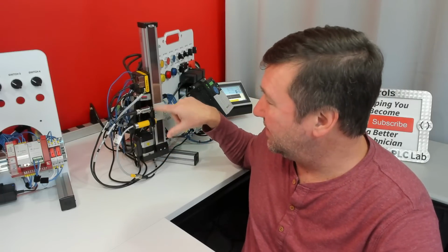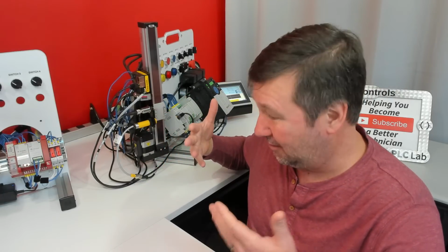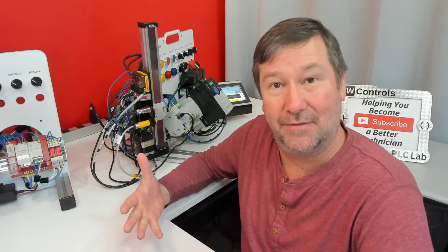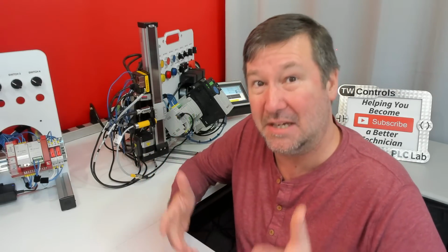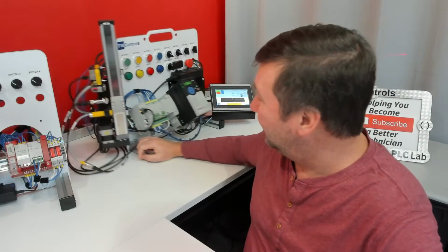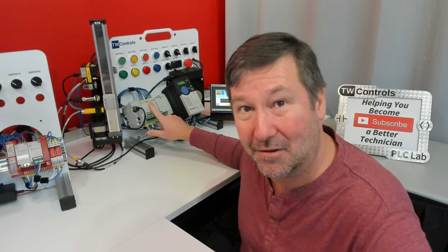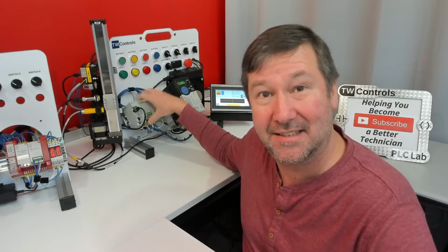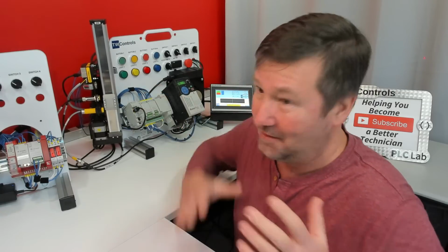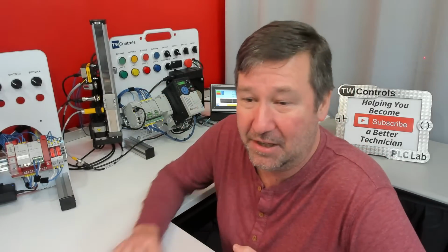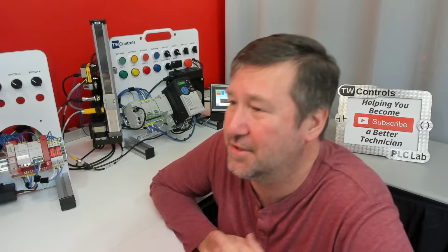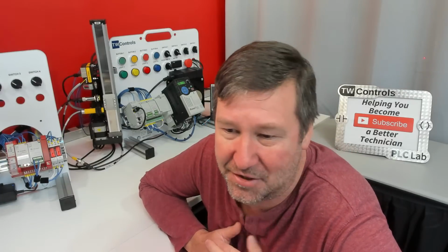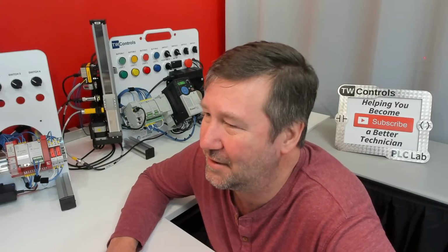Understanding these, looking at the diagram, figuring out: okay, how do I look at this and figure out, is it sinking, is it sourcing, or in their cases, usually, is it PNP, is it NPN? Then what can we handle in our PLC? In this 800's case, it can be sinking or sourcing. Okay, then what do we have to do? But yes, that video and 2 others go through it, and they should be out soon. In fact, I'm not even sure the one I just dropped in there has a title yet.